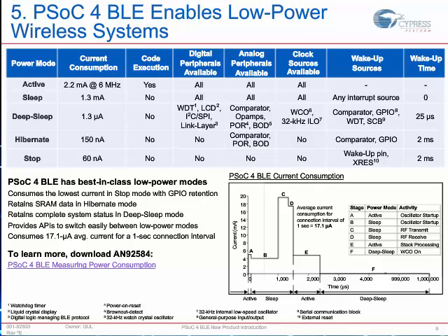IoT products and their battery life and their power consumption is not driven by how much current you consume in your active power mode, but rather by how little current you can consume in your low power modes. Because in reality, the way these systems are designed, they spend very little time, maybe 1/10 of their time in these active modes where they read the sensor data, get the latest condition data and send it over a Bluetooth link. But they spend maybe 80 to 90% of their time in these intervals of sleep modes